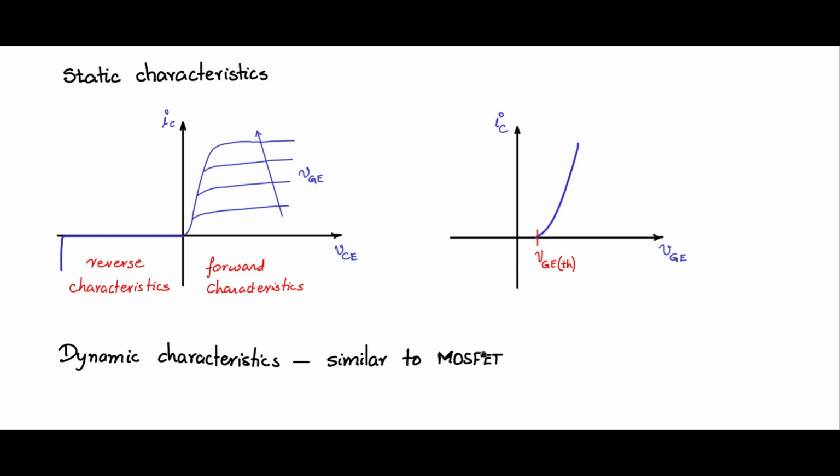Again, you have the conduction loss and the loss during switching, mainly caused during the TR and the TF times. So exactly similar to the MOSFET, there will be small changes with respect to IGBT to IGBT, just like you have in MOSFET to MOSFET, various MOSFETs. You can look at the data sheet to understand more about the individual specification values.